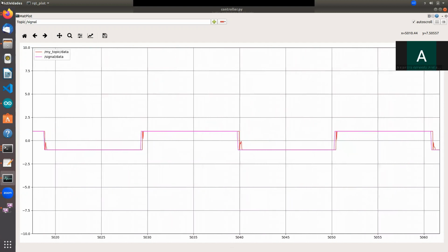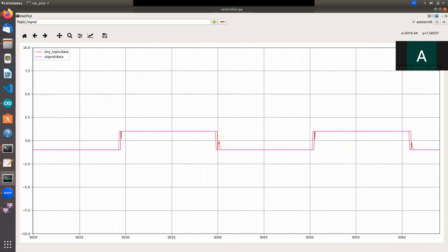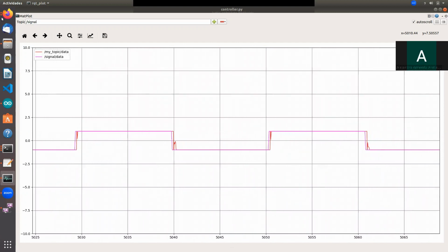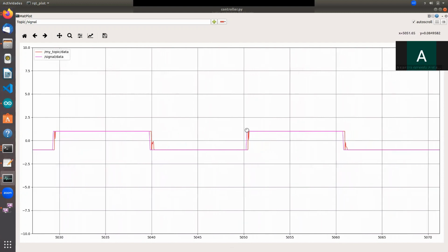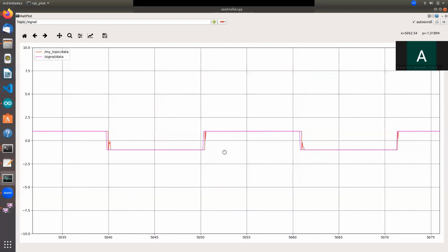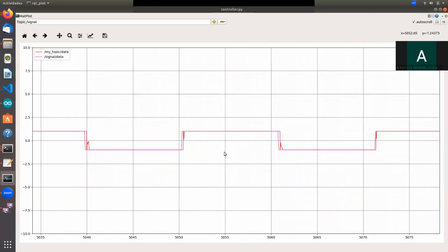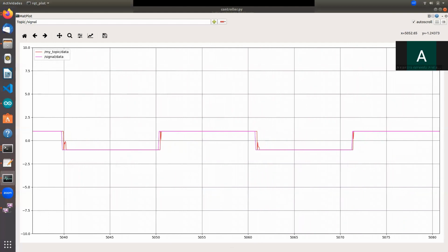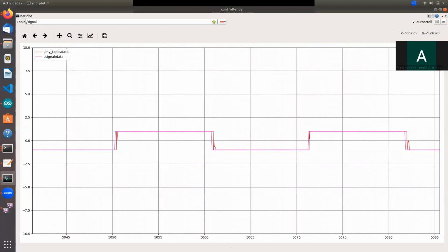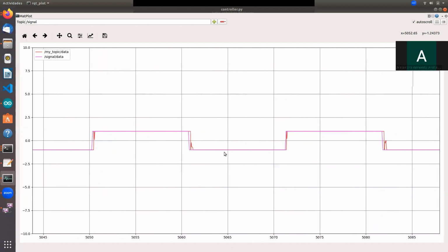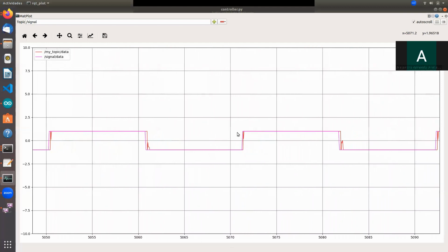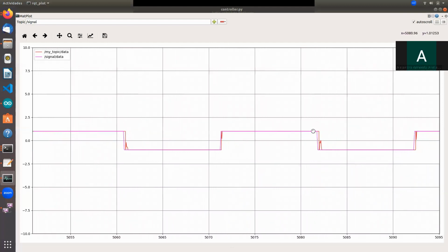This is a quadratic signal, and we can see how it reacts to our motor in real time. In the graph, you can see a small peak in this area, and this is due to the change in direction generated by our engine. When going at a speed of -1, in this case to the left, and later changing to the right, the system detects a drop in speed, when really the only thing that happens is a change of direction. After that, it recovers, and that is when the controller fulfills its function.